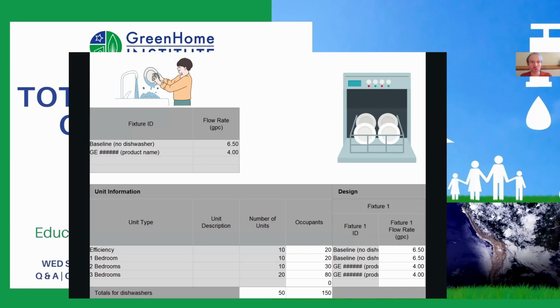Note that for LEED version 4.1 single family and version 4 multifamily, you must select one device in each unit under the Energy and Atmosphere section to be Energy Star certified. It can be from a list of three, the refrigerator, the dishwasher, or the clothes washer. Meaning, if one or the other two are not certified, you must install the Energy Star dishwasher. In this case, in most cases, the refrigerator is Energy Star certified. It's very difficult not to find that.